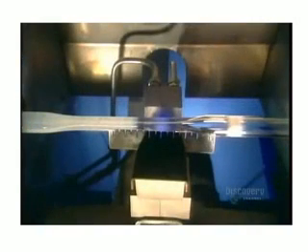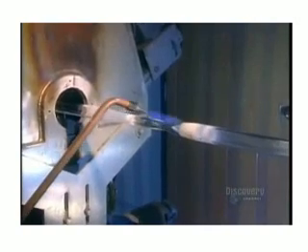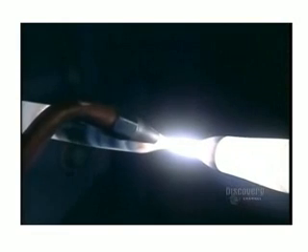The glass tube itself will form the fiber's covering. When there's enough fused soot, they turn up the heat until the soot itself turns into glass. Then they heat the glass tube enough to soften it, as well as the new glass inside. The intense heat eventually makes the tube collapse on itself to form a solid rod. The internal structure of the optical fiber has been achieved. But it's in the form of a big bulky rod called a preform, so the next step is to thin it out. First, they excise the preform from the uncollapsed section of the glass tube.